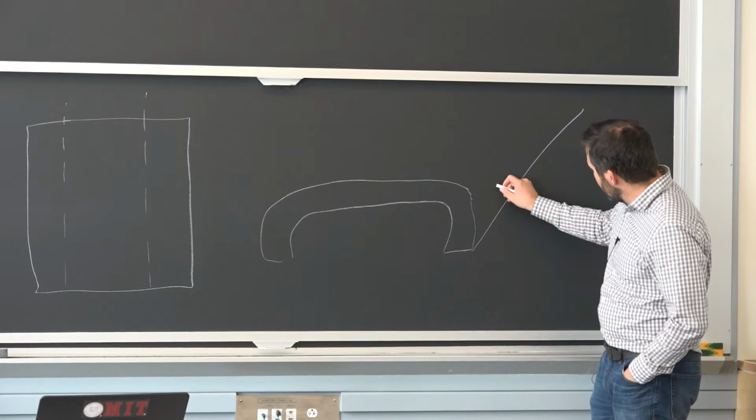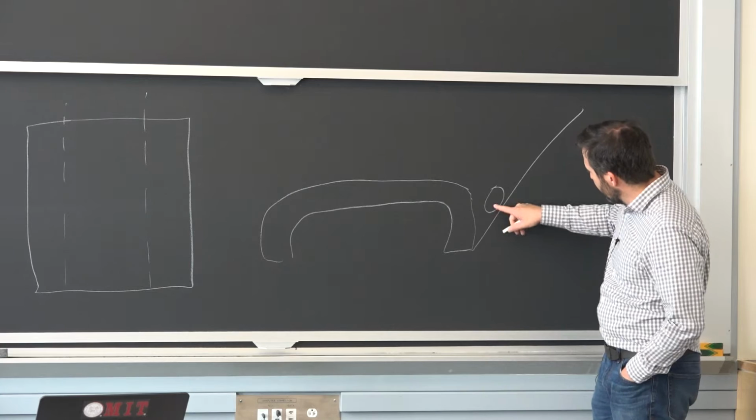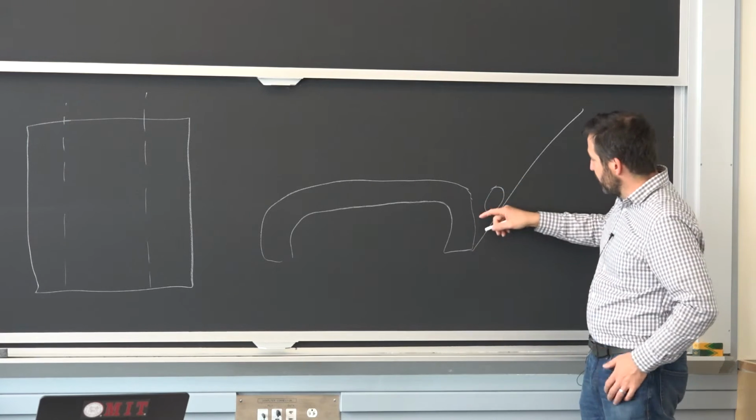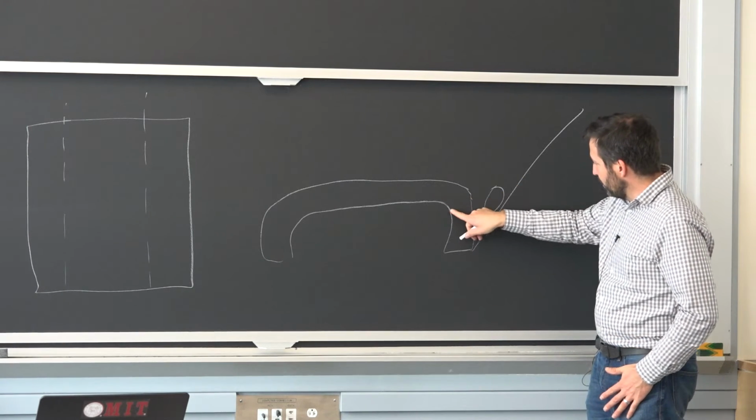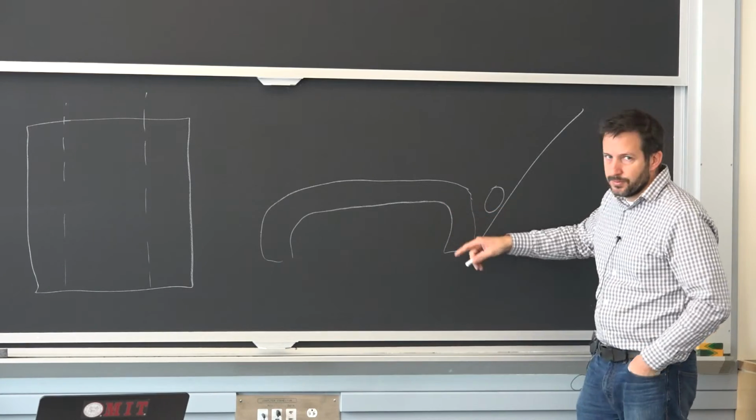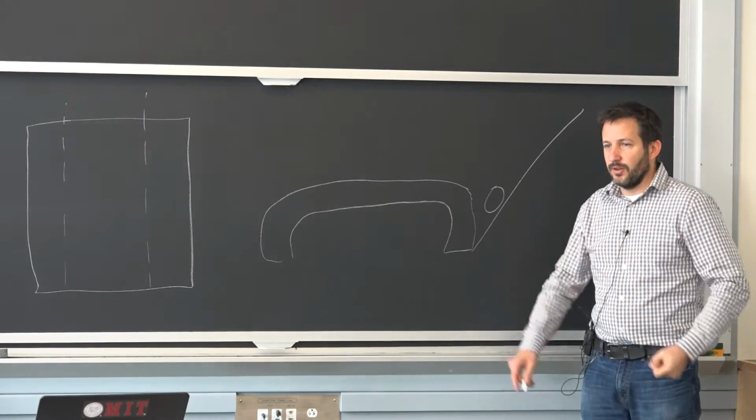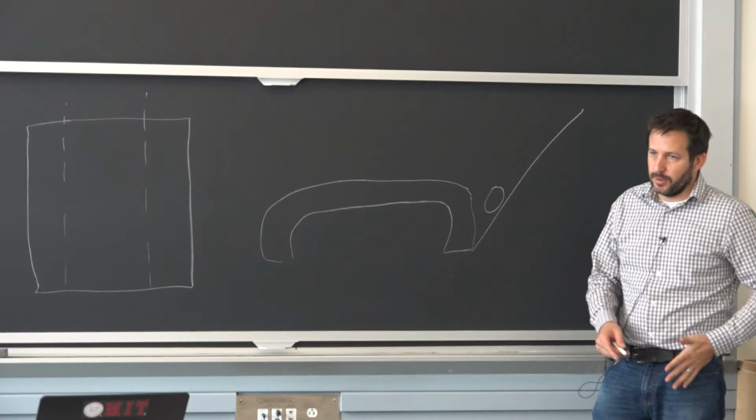And let's say we have our bolt holes right here. What happens is, when the arm gets bent, you supplement all these what we call residual stresses with the surface tension of pulling, and that's where the crack started in this case.